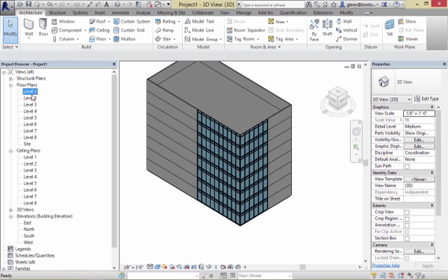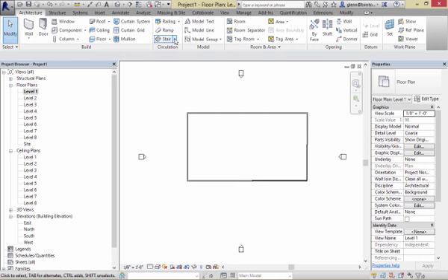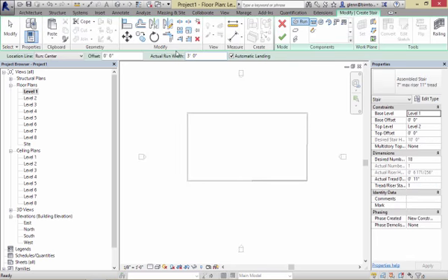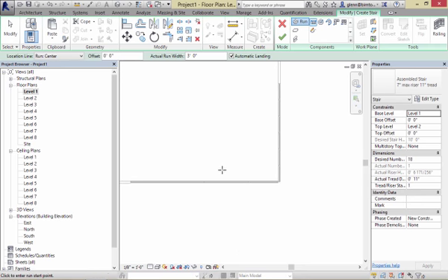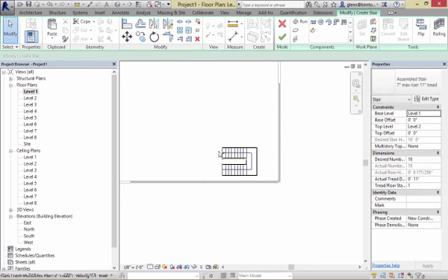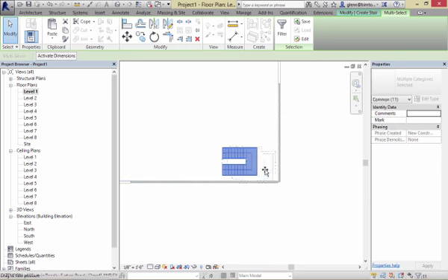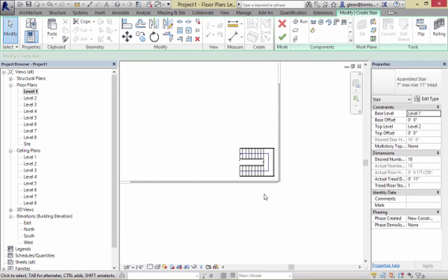So I'm going to go to level 1. I'm going to put some sort of stair in here. I'm going to say stairs, no worries. That's going to be fine. Level 1 to level 2. That's good. I'm going to put the stair over here. I'll come over about halfway. 9 and 9. I'll come over here. Got my little stair going there. I can even move this whole thing. Let me just move it all over so it's closer to the window. So I got a fantastic looking little stair here that's going from level 1 to level 2.